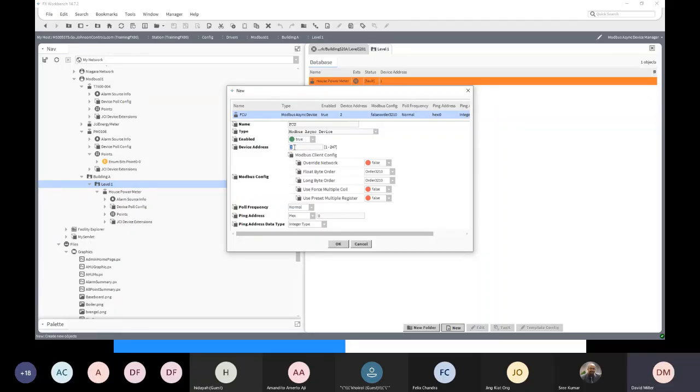So somewhere on that field device, there'll be a way to set the address, either through the display or with dip switches. There'll be some method for setting the address, and the address will be somewhere in the range 1 to 247. It might be less than that, but Modbus supports 247 addresses. In this case, we've chosen address number 2.